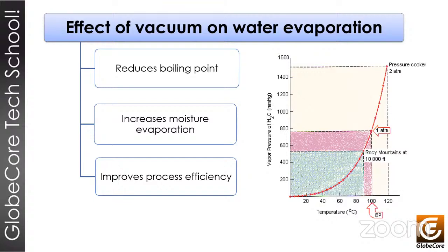The first important point is that when water is exposed to the vacuum, the boiling point decreases significantly. This makes it possible to extract water from the oil without dangerously raising the temperature above 65 degrees, where the oil begins to decompose to form water. It is important to know the value of water vapor pressure, or more precisely, the pressure and the temperature at which water evaporates.